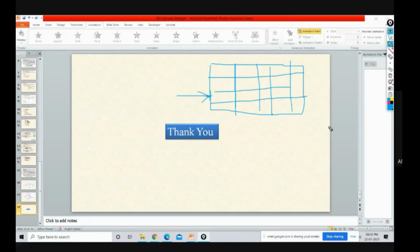Because the span is maximum for your slab, and if you go through that total span, obviously your depth will increase, correct. That is why we are converting the total slab into a number of slabs, the grid slab, to reduce the depth of the slab.